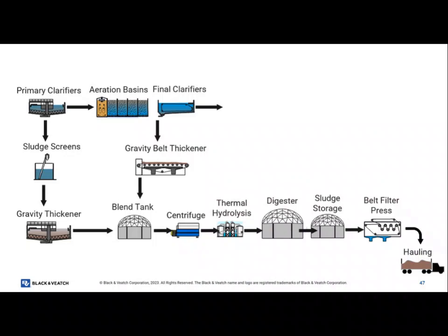Does anybody remember what kind of DO we had in this first zone? We had a 0.25 DO, so they started to see filament growth in the form of zooglea. And basically their SVIs went from 50 to 100. They had blankets taller than me. And that's one of the reasons I said they couldn't take deep flows. It was because this VFA coming in not only impacted the mixed liquor to manage it, but really started to impact settleability. And increasing air in this zone, they still couldn't catch up to it. There was just so much VFA pouring out of that selector because it's overloaded.